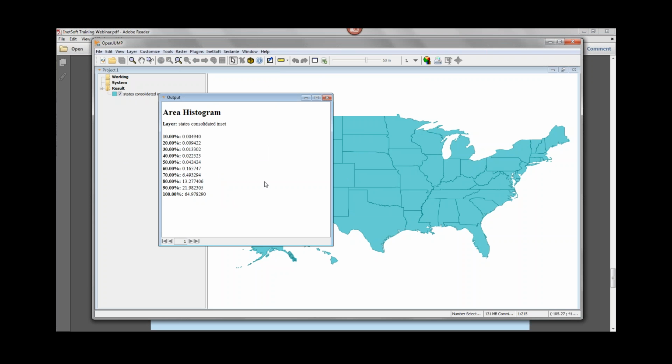Okay, so with this step, as with the subsequent steps that we're going to do, there's no absolute right answer to where you choose to threshold. Really, it's going to be based on the result, right? So you can make an attempt at picking a value, and when you look at the result, you can see, does the map still have its integrity, or did things get distorted? Did the boundaries get distorted? Did the shapes get distorted? If you're seeing too much distortion, then obviously you would back off on the number, right? So that you're removing fewer polygons. Right, so this is an optimization step, and you'll probably want to try it a few times to get the right value for a particular map.